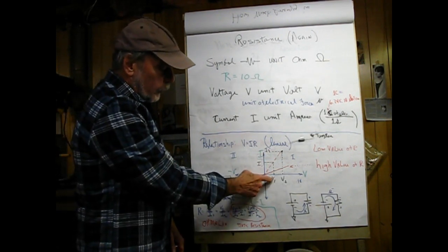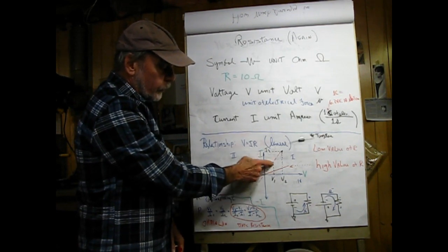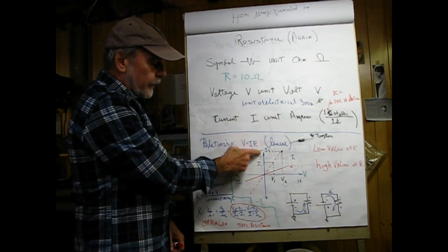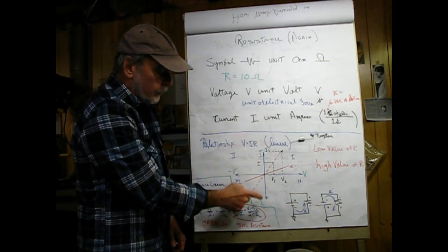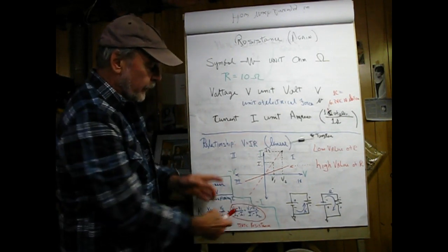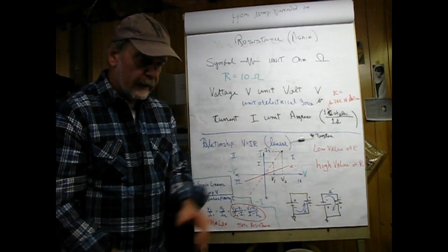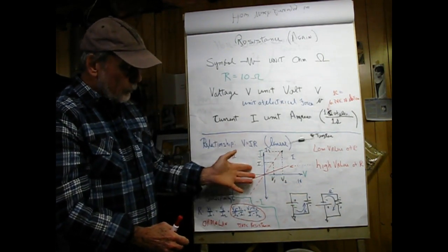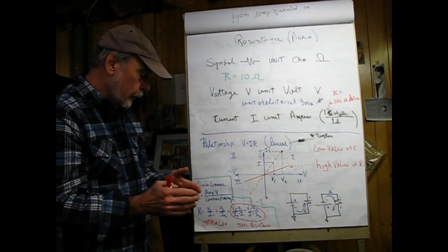Because for a given voltage, as you can see, the current in the first case would be here, current in the second case would be here. Speaking about current, that's going to be on the y-axis. Again, arrowhead, positive I, negative I. The negative I would correspond with a negative V for one of these circuits. I haven't defined that yet. There's a reason I haven't. So that's what Ohm's law looks like, and what's very important here is you see that it's linear.